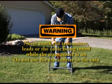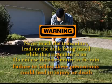Never touch the transmitter, leads, or the cable being tested while the transmitter is on, and do not use the transmitter in the rain. Failure to follow these precautions could lead to injury or death.